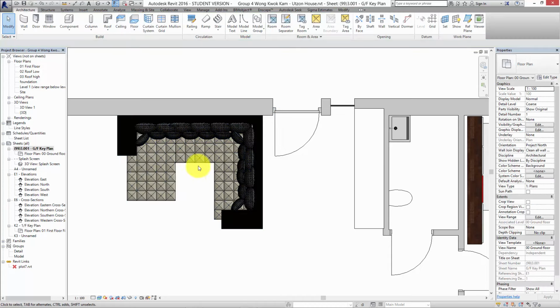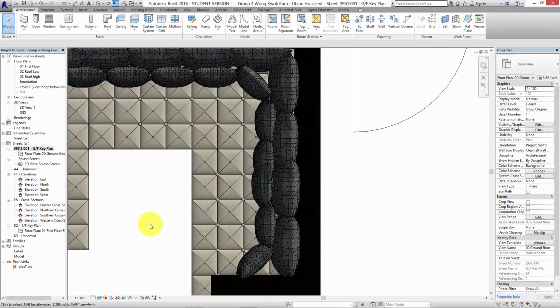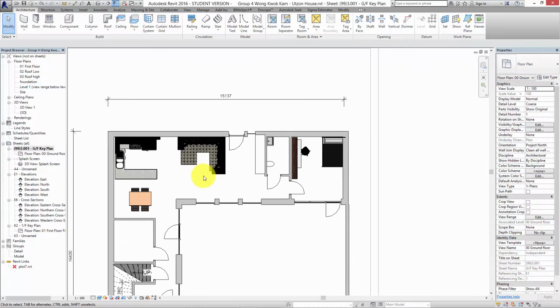That was my first idea, that it was made by a student, because they haven't changed how it represents itself in a plan view. You can modify the families so they look funky in a 3D view, but in a plan view they're just a line drawing, so they don't fill up. You see how much information is in this drawing? It actually draws your eye to it, so you're taking it away from everything else.